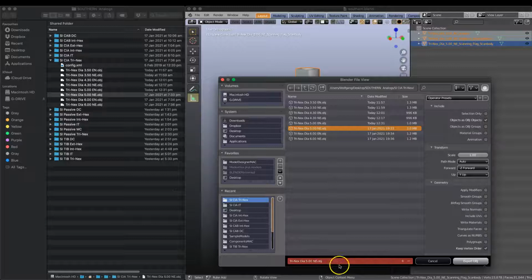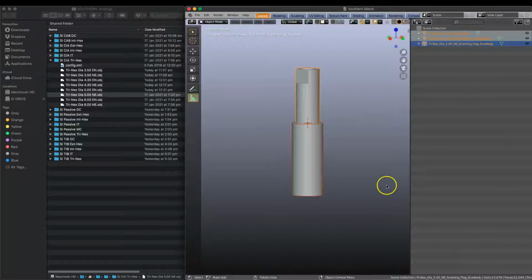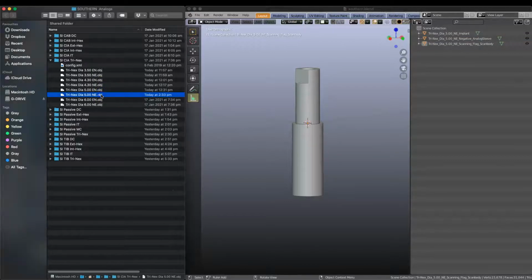It is red down here at the bottom because Blender is telling us we're going to override something. Make sure the component names are correct so that they're correctly matching in your Explorer and in the Blender window. And then you're going to just push export. Okay, wait for that, and then it's going to update here in the Finder window. Just wait for it. Here we go.